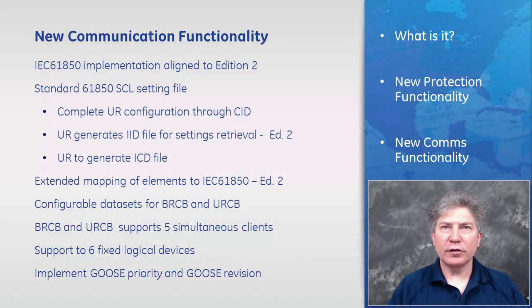The new communication functionality focuses on the implementation of IEC 61850 Edition 2. It includes standard 61850 system configuration language files such as CID, IID, and ICD files. We'll discuss the role of each file type. There's a list of extended mappings of elements within the UR relay for 61850 Edition 2 as well.